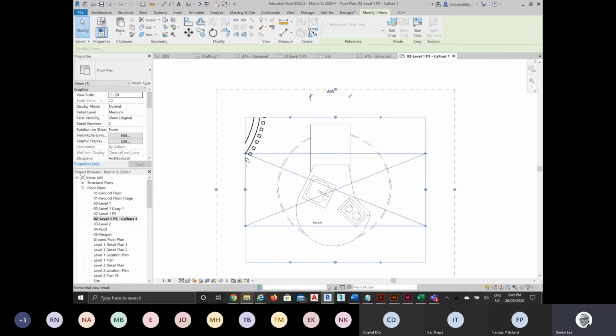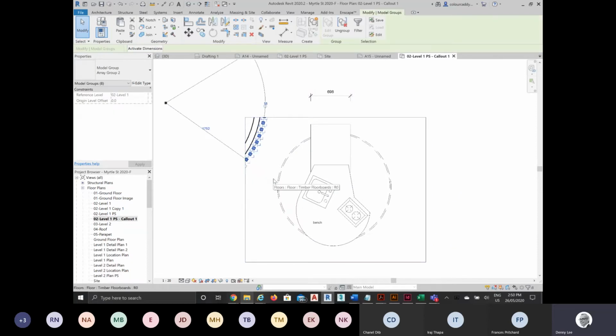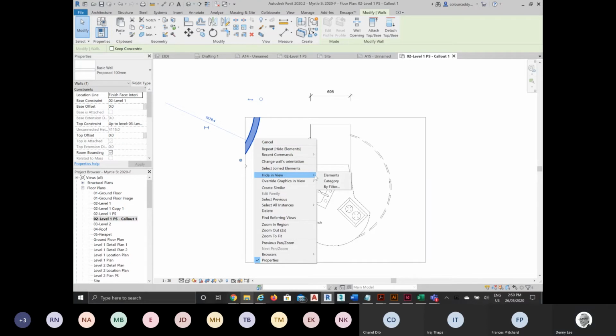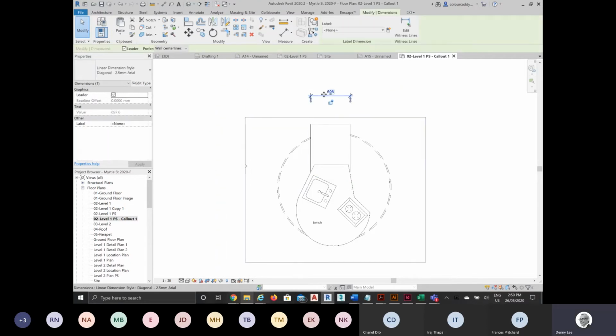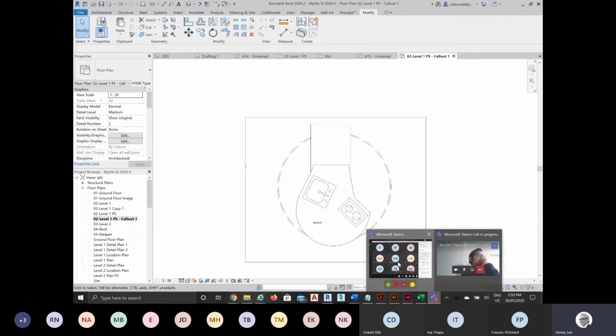And you can see I'm getting some other elements coming into this drawing. If you don't want those things to show, again, don't overcomplicate it and try to use cropping to get rid of those things. Often it's easier just to hide things like that. Just hide by element. Get rid of that dimension. And so then I can make additional elevations from this view.